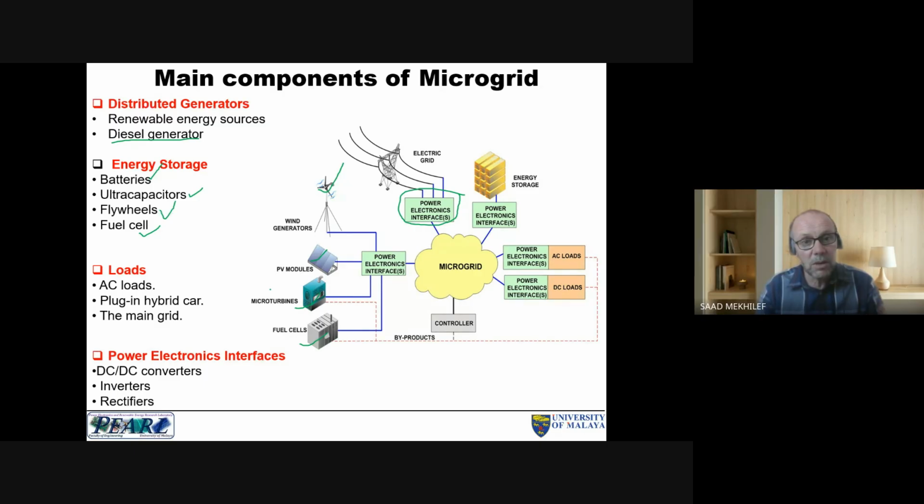That's why you can see the research in power electronics. Now we are moving from grid following to grid forming inverters. These grid forming inverters need to help stabilize the frequency of the grid, not just inject power. Before, it was only injecting active power, then reactive power, and now it has to help in stabilizing the grid. So that is the future: to move to a green grid, which is mainly from green resources. Sometimes we also see a carbon neutral grid.